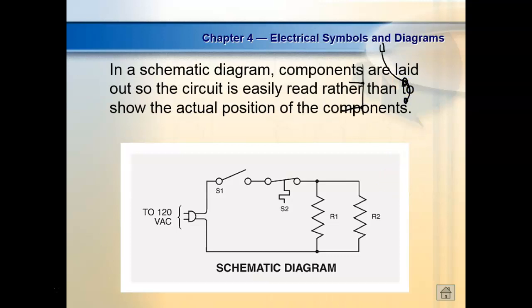But they think because it's drawn that way, they'll have L2, and they'll say, I'm going to run L2, and they'll just start jumping. So they're over here separated, like one's down here and one's up here, but they think they got to go way back up here when they're beside each other, just because it's drawn that way. So circuits or schematics or diagrams are trying to show how the circuit logically works. It makes it easier to troubleshoot. It's not how they're wired. It's just easier to understand how they work, right? You understand that?